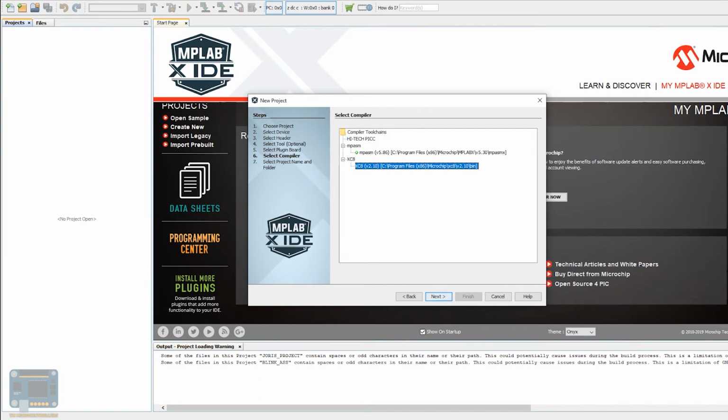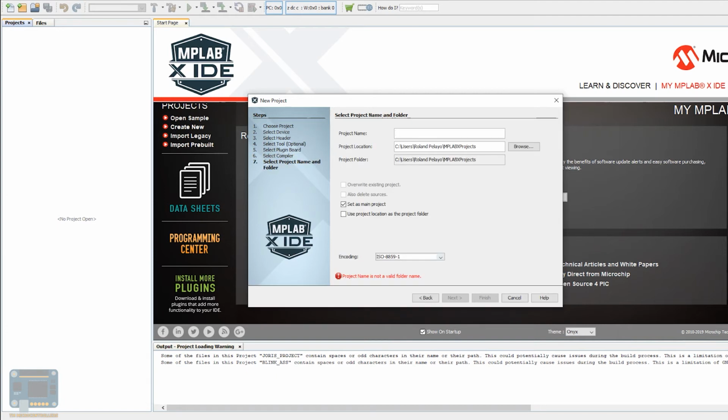Then your XC8 compiler will appear here. So I'll be just giving you the links for the installers, maybe in the description of this video. And okay, going back, you select XC8 here, select Next, then give your project a name.